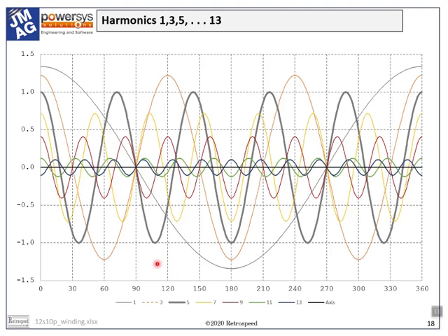Anyway, the final message is that the basic operation of the machine is based on the fifth mechanical winding harmonic, the working harmonic, and all other harmonics contribute parasitic or second order effects. They do not participate directly in the production of average torque.